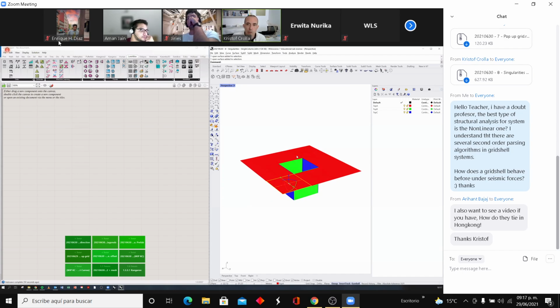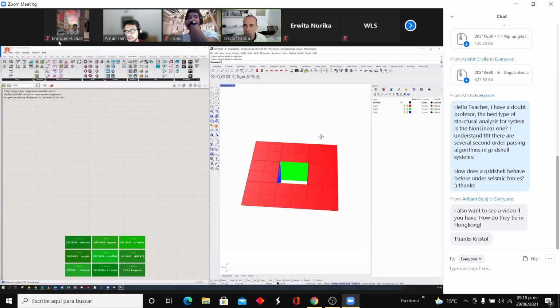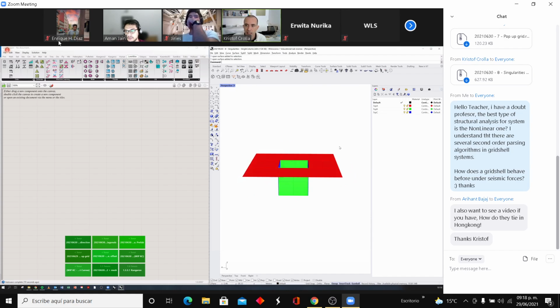And then the idea is that we use these planes to generate diagrids on it. Then we'll use Anemone to connect all the curves together. And then we'll bring that into Kangaroo, and then we'll pop into Shape. And then we'll go through all of the challenges of offsetting, putting your mesh through it, creating diagonals, etc. So we'll see how we go. But the idea is that with this setup, that's basically your starting point.